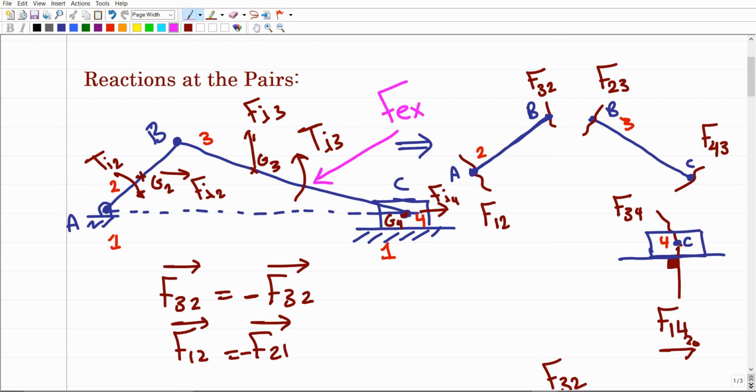Makes sense? Especially for this case, it is recommended to skip the external force, or you can even add the external force. It's going to be clear as we proceed with the example. But anyway, your objective is to combine all of these forces into one equivalent force over this link. The same thing here, we have 2 forces, so we combine them into one equivalent force, and so on. This is the third step.